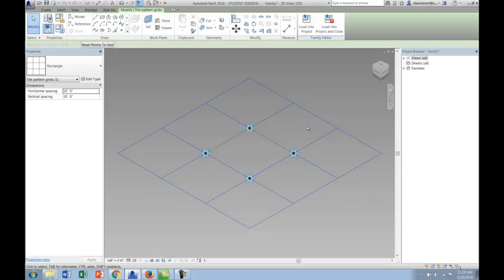If I select the grid in the background, you can see over here that it pops up with a rectangular reference. And when I look at the drop down, there's all of the exact same references that you had from the other tool, from the divided surface tool. So these two things go together hand in hand, right? The curtain panel pattern-based conceptual mass works hand in hand with the divided surface of a conceptual mass. And so the 4 reference points that you see here would reference a traditional grid, and they're going to get deployed across, just like we did last Thursday.